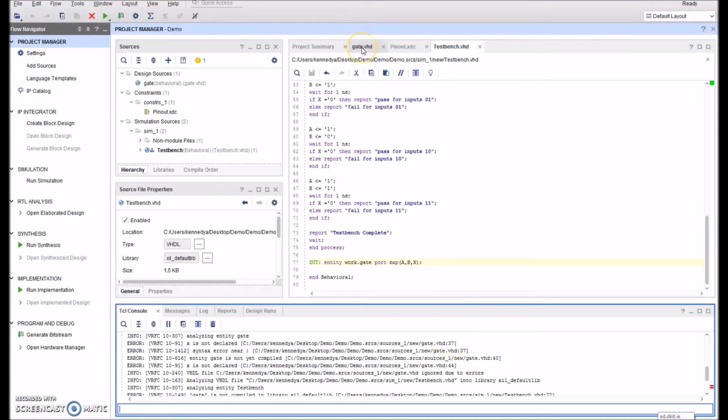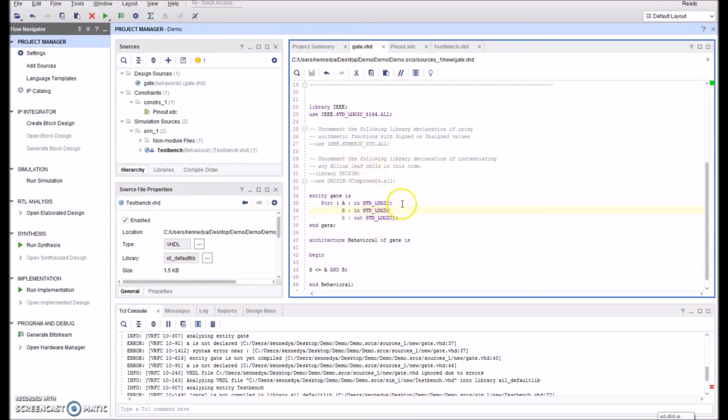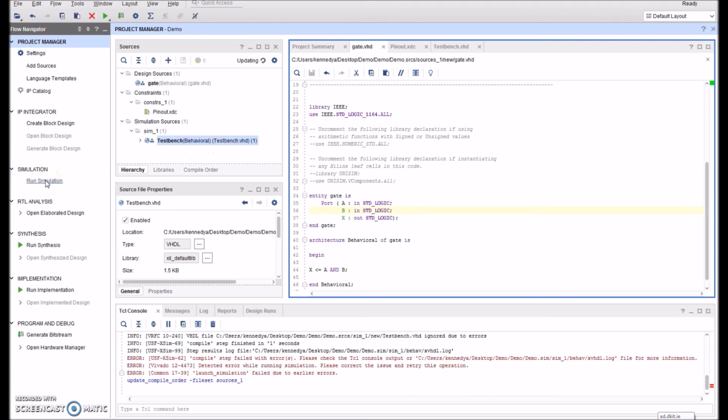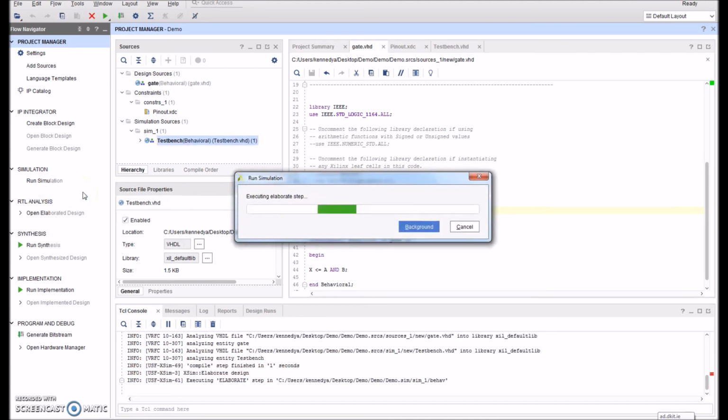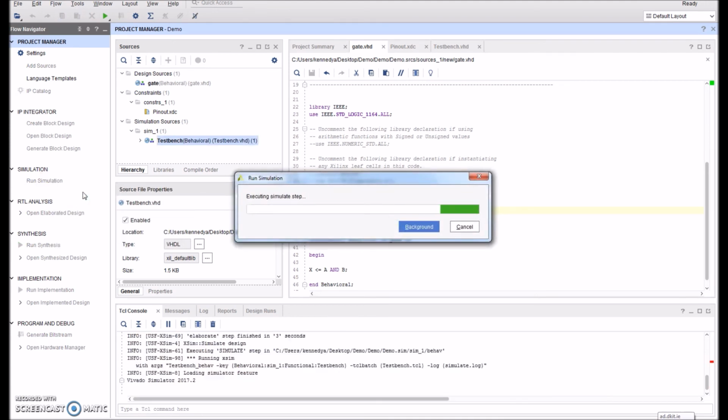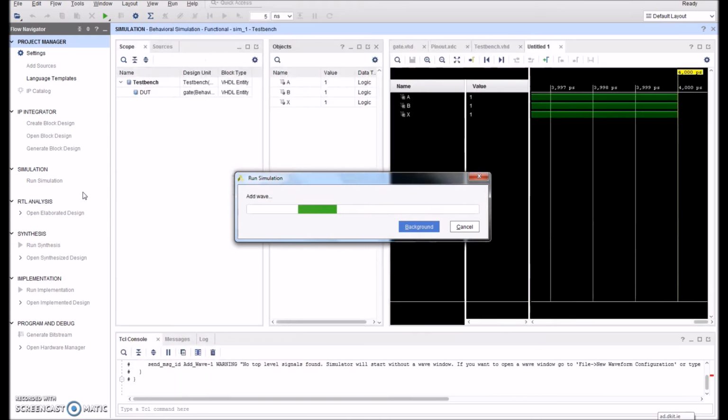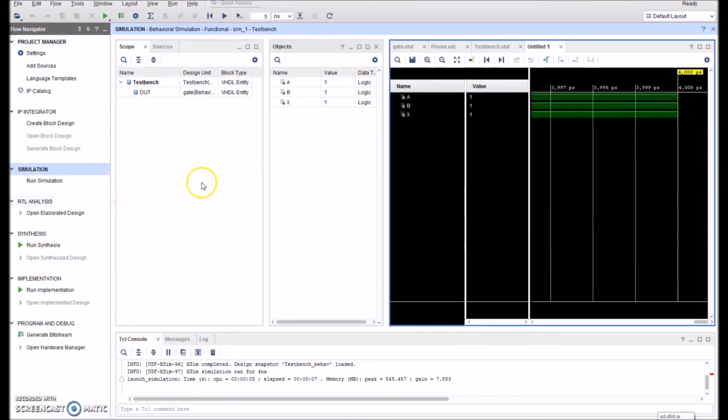So if we go to line 37, we can see the semicolon that we left out on line 36 is our problem. So we'll keep running this simulation and checking our TCL console until we found all the errors. So that's the only error in our code.